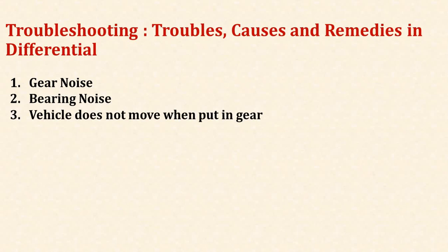The next cause of gear noise: broken or damaged teeth of side gears or differential pinion gears. So the remedy is to replace them. Then the next trouble, the second one, is bearing noise. The causes are damaged or worn bearings or worn parts, with constant noise. The remedy is to replace them.